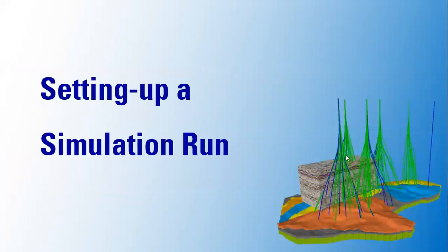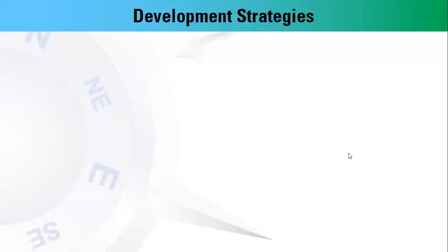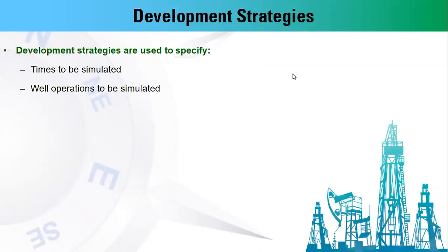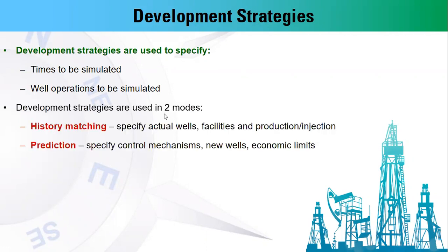So to set up a simulation run, simply we have the development strategy. The development strategy is used to define or specify the times to be simulated, the start and end time for the simulation run, and also will define the well operations or the depletion strategy to be applied in the field.